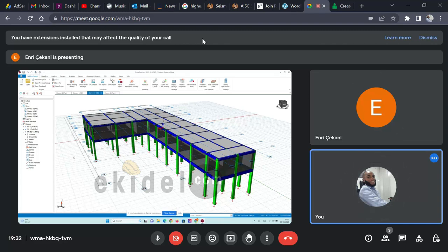That will form a good connection between the beam and the column, and when there is a shake or vibration, it will help a lot. Because if you use a different spacing on the joint between the beam and the column than on the column, when there is vibration, that joint between the beam and the column will fail. It will cause what they call drift, or uplift, yes, it will cause uplift, because that joint is not strong enough, or not firmly connected with the column. So always use the same link spacing you use for the column also for the beam, but only to some certain percentage.